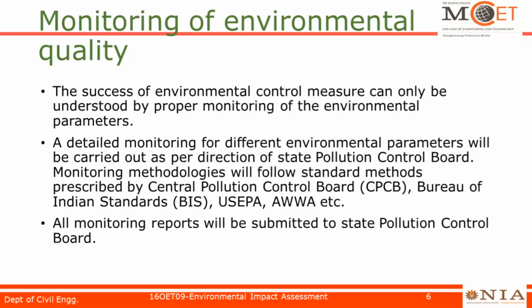Monitoring methodologies will follow standard methods prescribed by the CPCB, Bureau of Indian Standards, US EPA, AWWA, etc. All monitoring reports will be submitted to State Pollution Control Board. So here US EPA and AWWA are for other countries. For us it is CPCB and Bureau of Indian Standards.